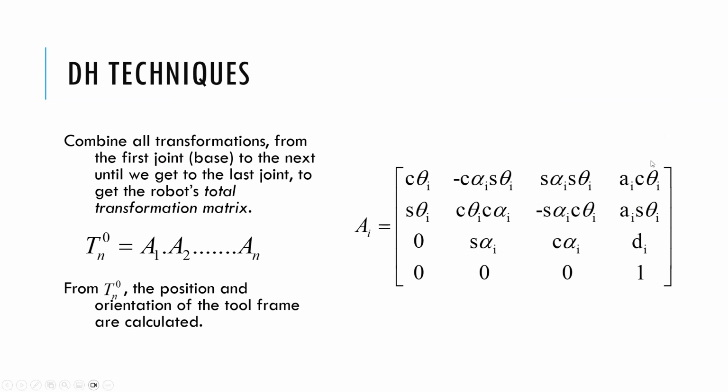That's for transformation. How about rotation? So your rotation is just the 3x3 component of this, and you would need to extract your roll, pitch, and yaw from it. The rest of the distance will be the same. So if we do a rotation only, only the 3x3 would be changing, is that correct? Yep. If you just do a rotation with no translation, there's only the 3x3 that changes here. Okay.